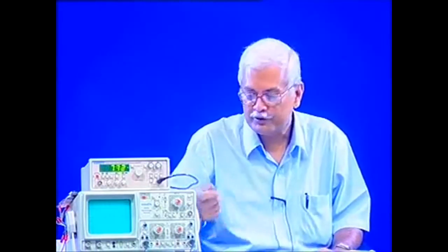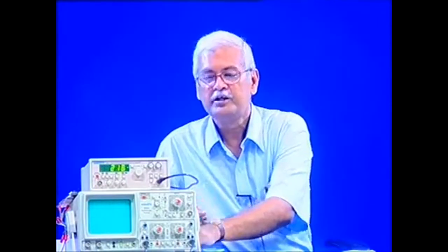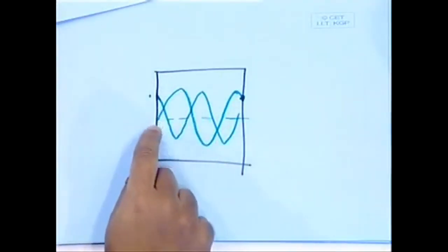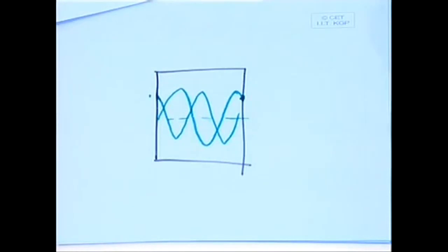So, what do we do for that purpose? Actually, for that purpose, the oscilloscope has certain very sophisticated features called the triggering of the oscilloscope. There are some trigger controls available, and using the trigger controls we can make the waveform get triggered only with the signal, so that it starts the next journey from the same starting point once more, so that we will observe the waveform like a static waveform.